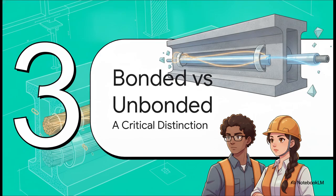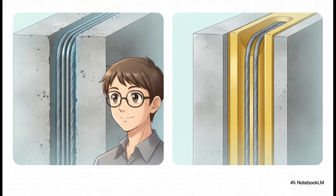Before we calculate anything, we have to understand a critical distinction in Indian design practice. We have bonded tendons and we have unbonded tendons. With bonded tendons, the steel is grouted directly to the concrete. That means at ultimate load, the strain in the steel is directly compatible with the concrete right next to it. For this, the IS 1343 code tells us to use Table 11.